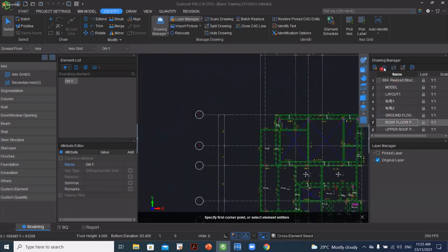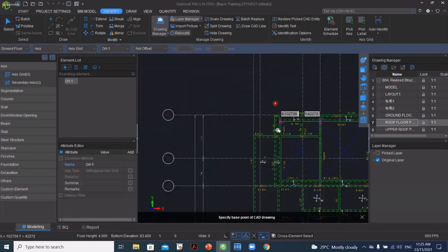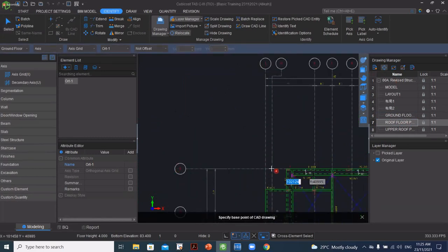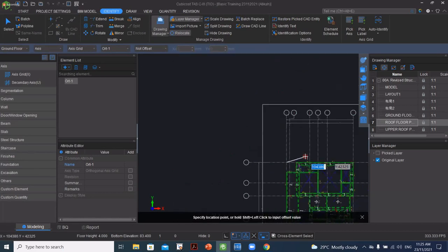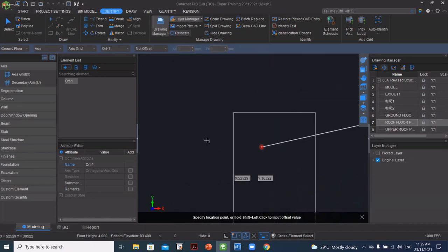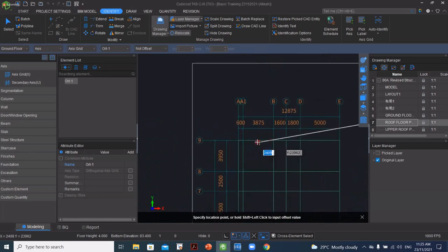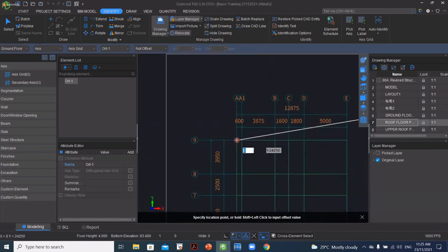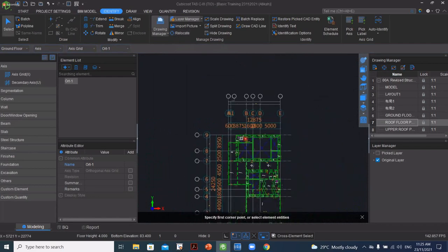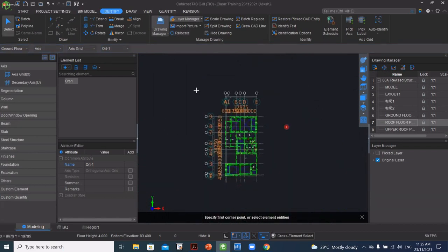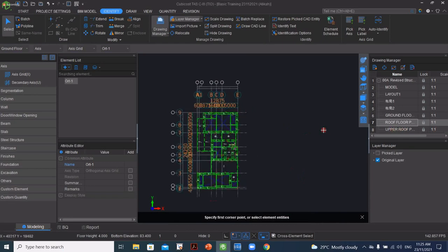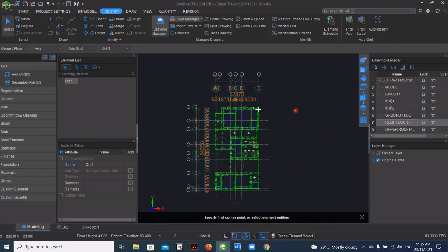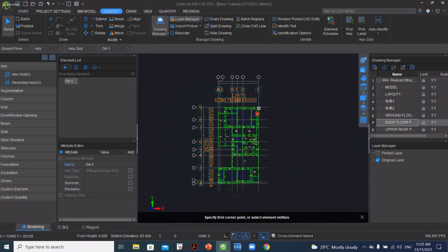this function. Just click on this relocate function and then select the intersection between grid line 8 and 9. Select here and then drag it, and then select the intersection of your axis grid line just now. Then you can see that your drawing is being relocated to the axis grid line. If you're done relocating your drawing, you can put in the chat as done relocate.